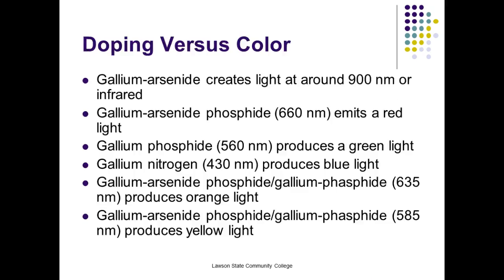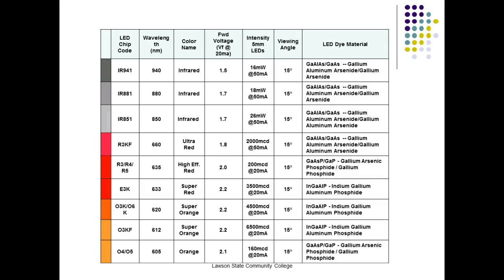Well, you look at a data sheet, right? You understand. And then your data sheet would tell you the current. So this guy right here says, okay, I want to do what? 50 milliamps. Now, normally we don't run it at its maximum current. That's maximum current. Normally we run it at about half that, and then this would be the VF. So this is what we want: 20 milliamps. So that's my current, right?